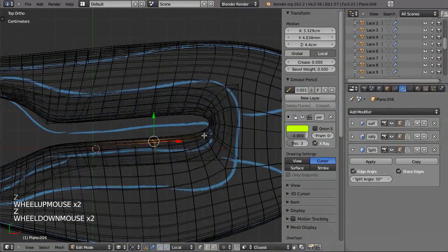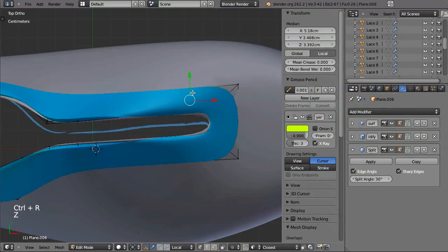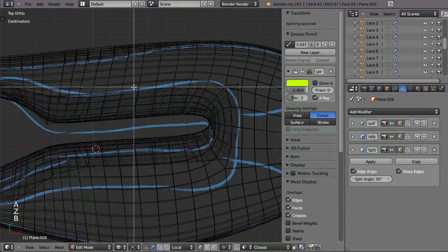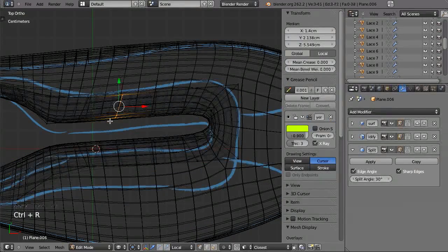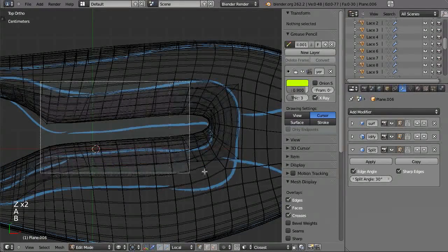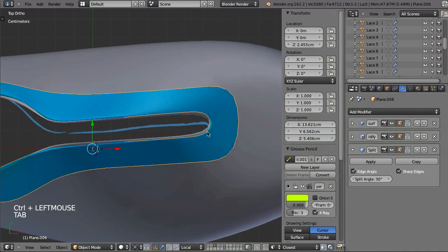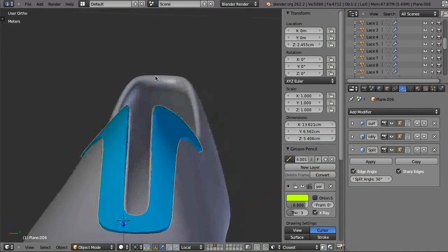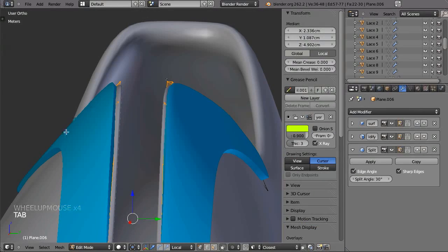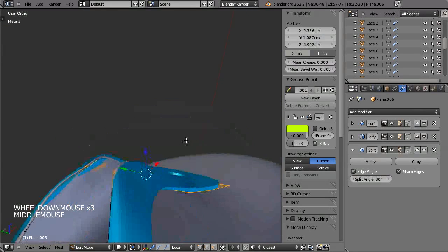And as you see, this one doesn't really look very good. Same here. It's difficult to get the details, so I'm just adding a little bit more geometry by locally subdividing those parts, and then I can select all those again. And let's say first, go back into edit mode, G, control, snap, see, much better. And then of course in the next step I could start pushing those back slightly a little bit.